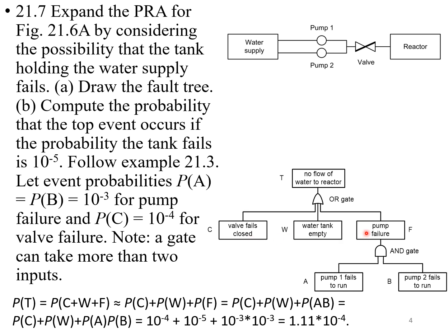Another one is the pump failure. The pump as a whole system, it contains two subsystems. So that is pump 1 and pump 2. And to have no flow to this valve, we need to make both pumps to fail. Therefore, below this one we have an AND gate. And this AND gate will have two basic events. That is pump 1 fail and pump 2 fail.